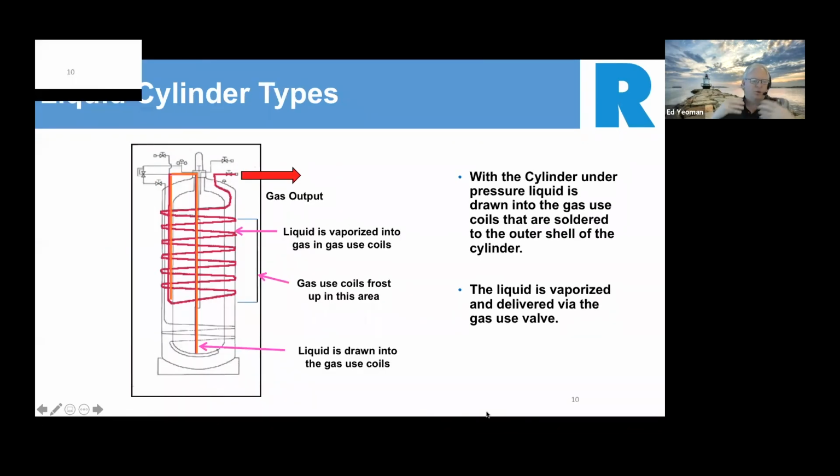So this is showing you gas use. So when you want gas output from a cylinder, which everybody should realize, maximum gas output out of a cylinder downhill with a tailwind on a good day is 350 cubic feet an hour. Again, the pressure builder is working in the background. It's doing its thing, it's building pressure in the cylinder.